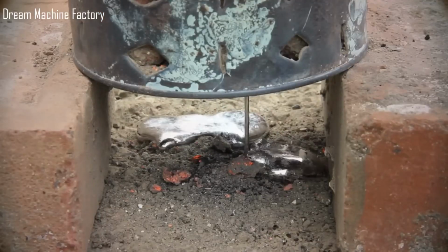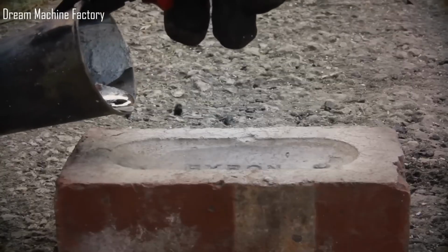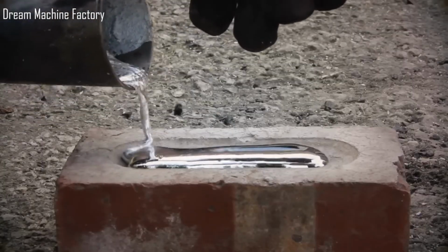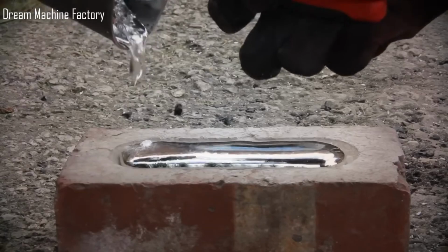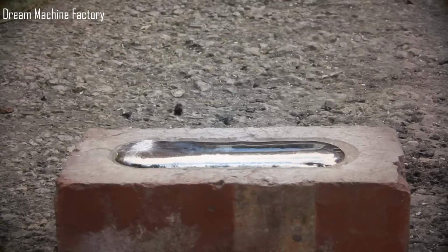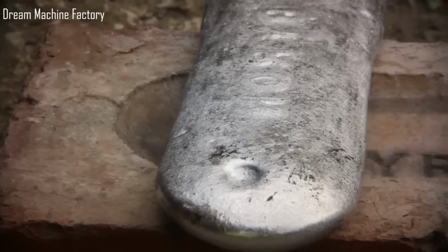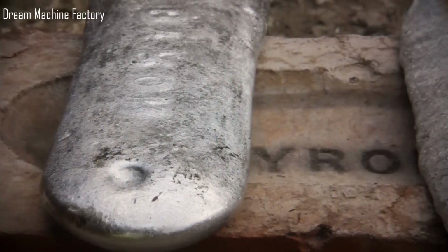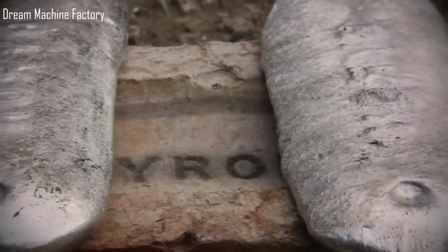When the aluminium is fully molten, carefully lift the crucible with steel pliers, avoiding plastic grips that might melt. Pour the molten aluminium into a prepared mold, such as a sand cast. Always wear gloves and goggles, and work in a safe, well-ventilated outdoor space away from flammable materials.